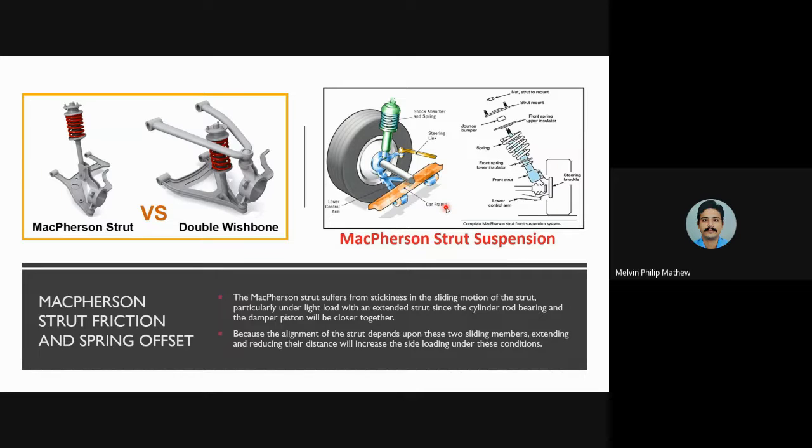So what is the advantage of front wheel drive? We know the various components that are present for rear wheel drive. From the gearbox, it goes to the propeller shaft, from the propeller shaft to the differential, and then to the rear wheels. That is how power is transmitted. But this long distance of power transmission results in a loss of transmission power.